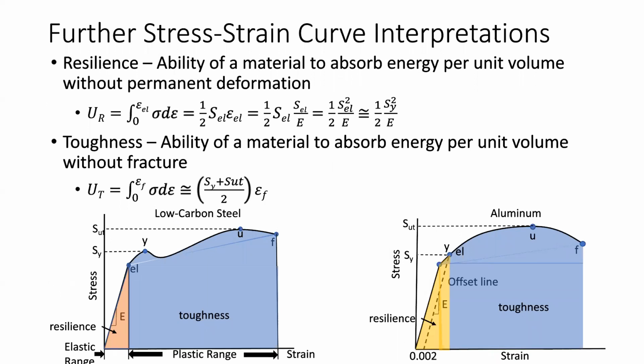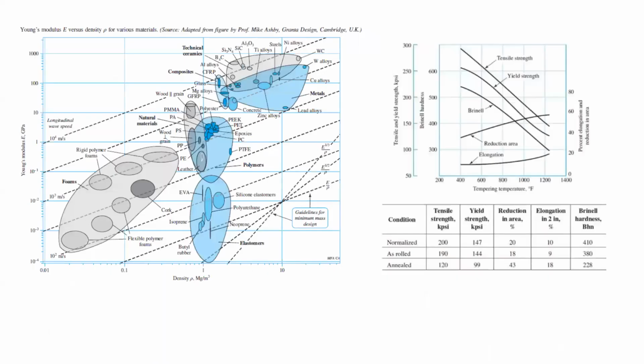For really high peak loading conditions, you might also think about how much energy can my part actually take before it passes the yield point. So we had already talked about it a bit last time, so I won't go into too much detail, but you have these integrals of the stress strain curve up until the elastic limit. So that's basically asking the question of how much energy can my part absorb before it permanently deforms.